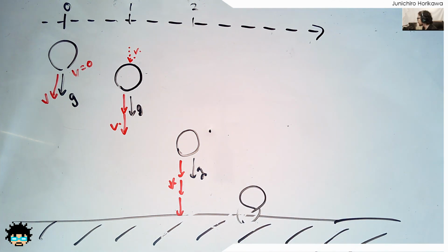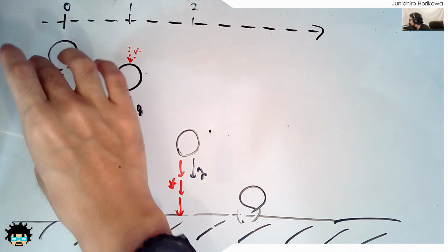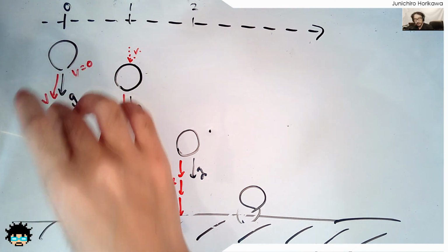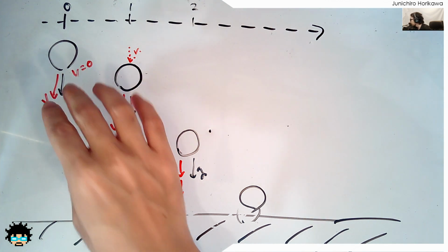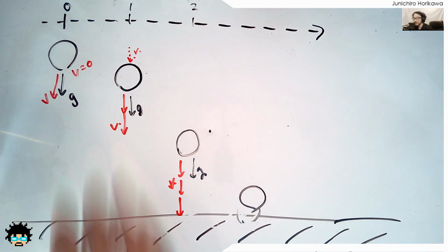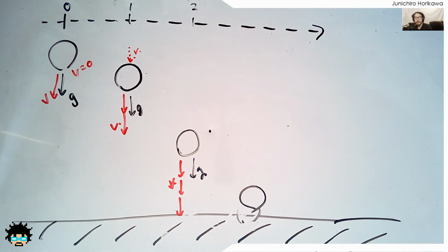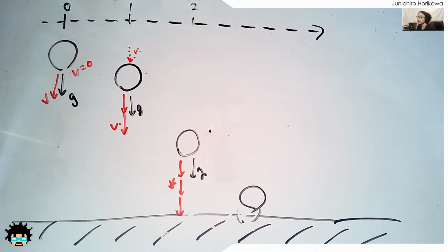So what's important here is the relationship between the position of the object, the velocity, which actually moves the object using the vector value, and the force value, which will be added to the velocity, which is also a vector value. This is the essential relationship you need to remember. First, you have the forces being added to the velocity, then you use this velocity to move the object in a specific direction. And by understanding the basic relationship of this force, you'll be able to easily implement this physics in any kind of environment, including Houdini.